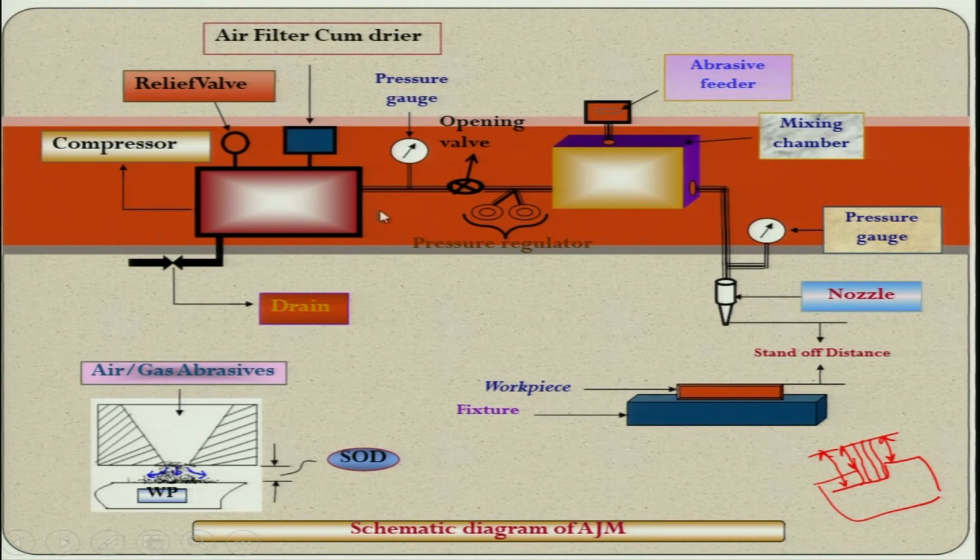Let us see, again the compressor is there, which will raise the pressure of the air or the gas that you are going to use. This is the relief valve over here, this is the cylinder where you are collecting the air or the gas, and this is the drainage for whatever is left over there, you can drain out before really refilling the cylinder.